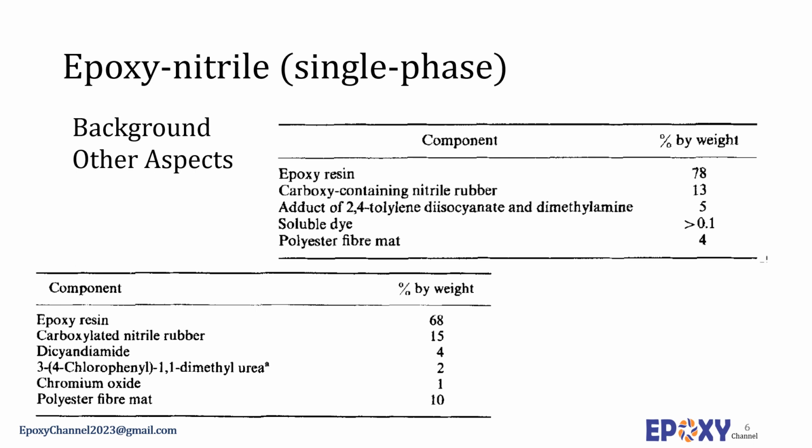The nitrile epoxy adhesives also provide better resistance to moisture. Employing nitrile in the epoxy systems often results in a degradation in heat and chemical resistance. Typical composition of these formulations has been presented here. In commercial samples, often diglycidyl ether bisphenol A systems are used and DDS is used for curing.